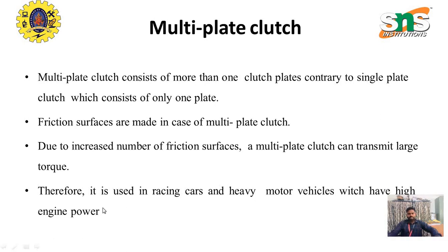We use the multi-plate clutch where we require large torque to transmit the load, and therefore it is used in racing cars and heavy motor vehicles which have high engine power. In racing cars, we have to generate a large torque in a very short span of time, so we use the multi-plate clutch for an instant rise in torque.